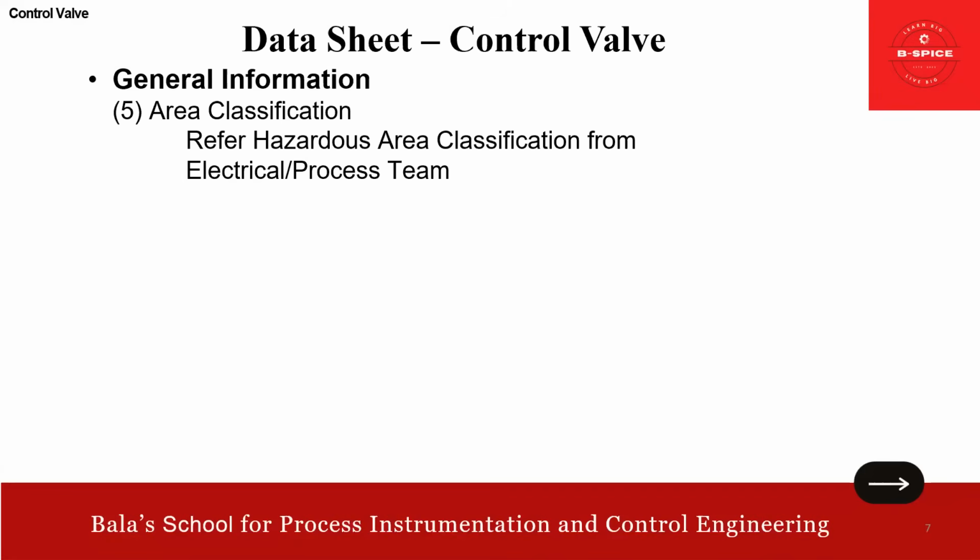So here I want to say some very critical items. In a refinery or a petrochemical plant, generally they are processing flammable fluids. Hence, the majority of the areas where instruments are located will be zone 2 area classification, or zone 0 or zone 1. It purely depends on the hazardous area map. So that is the first thing, the hazardous area.